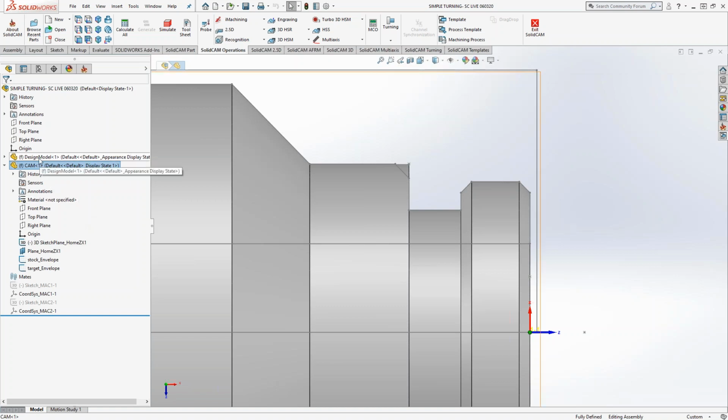Well, the sketch is gone only in design model, right? CAM, it stays? Oh, I'm sorry. Yes, in CAM it would stay. Sorry. Yeah, I think the difference is exactly what you're saying. It's a matter of associativity. It's design model versus everywhere else. So you'll lose that sketch if you do it inside of design model, because that's going to be associative to the current design model. So like Kevin said, if you do a change model reference, the difference between CAM and outside here, the sketch itself, there's really no difference.